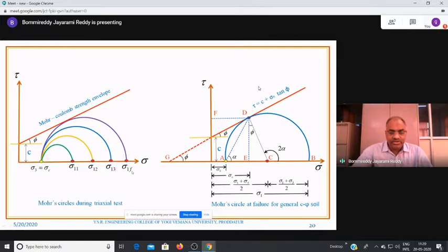That is called sigma 1 f. Sigma 1 f means the first sample has a cell pressure of sigma 3, and its major stress will be equal to sigma 1. At the time of failure, what is the stress? That is important. So for the outer principal Mohr circle diagram, draw the tangent, and it will intercept the y-axis at a point at a height of c.